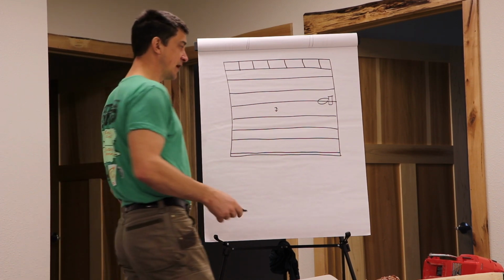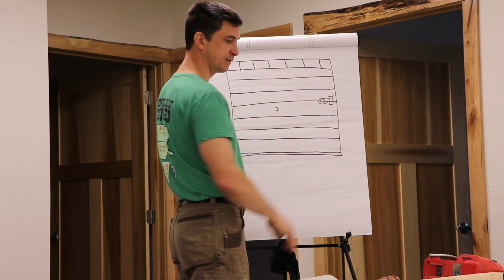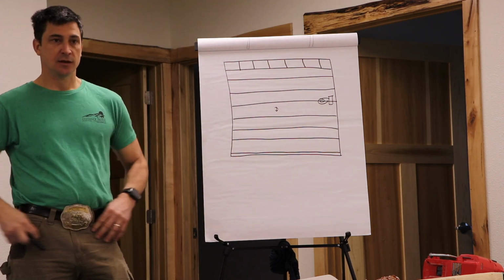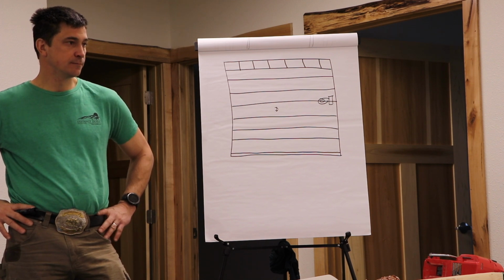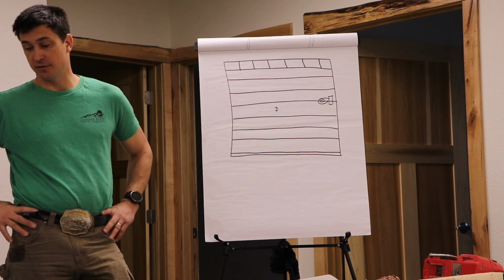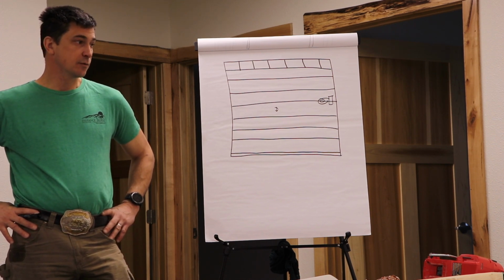And they go in the bathroom and they mark their hole and they cut their floor, and the joist is dead center. And they're like, what do you want to do? And then you got to figure out, are you going to move the toilet, or am I going to put another joist in?